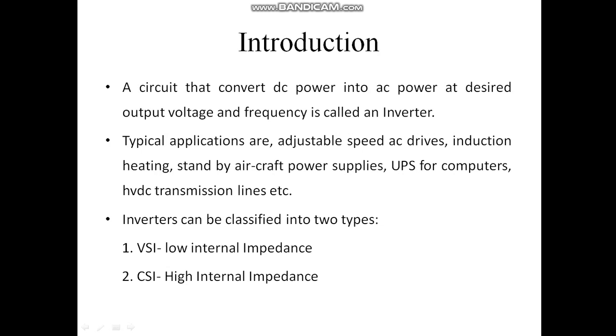Now in voltage source inverters which use thyristors, some type of forced commutation is usually required. If I am using thyristors, then obviously, a thyristor is not a gate commutated device. It requires the gate just to turn it on, but to turn it off, we require some external circuitry. We may also be using BJT, MOSFET, IGBT, SIT.